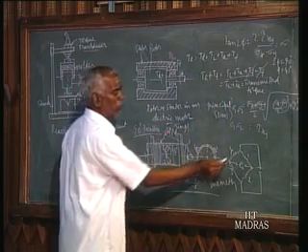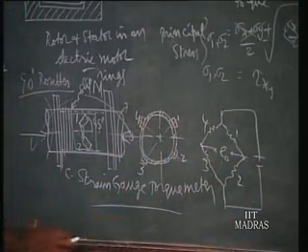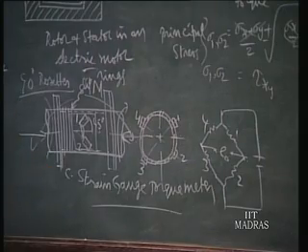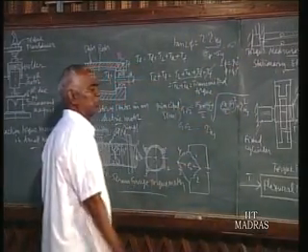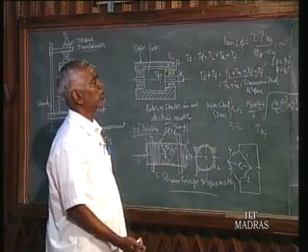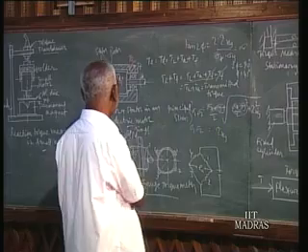4 slip rings for the 4 corners, 2 corners for the supply, and the 2 slip rings for taking the output signal. So by using slip rings, we can take the signal inside and signal outside. If it is a stationary shaft, such things are not required. So it is an easy method of measuring the fixed shaft by using the strain gauges. It is easier.